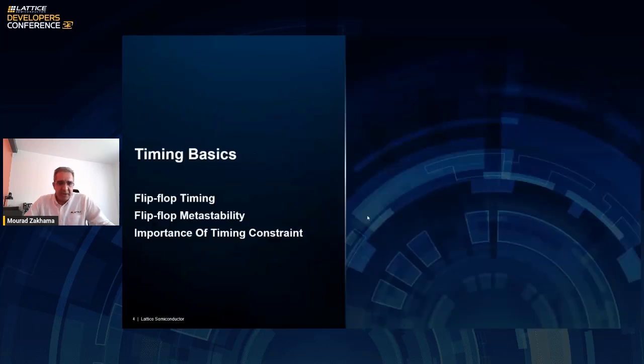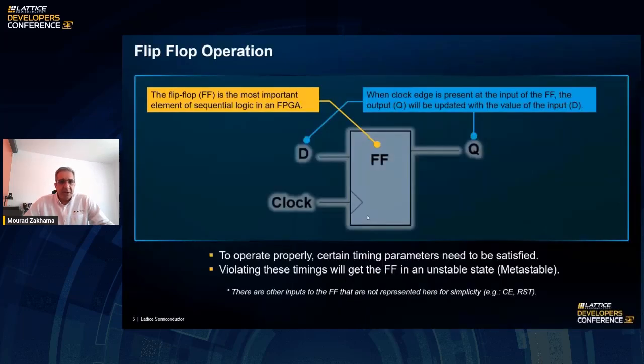So let's start with the timing basics. We're going to talk about the flip-flop timing, the metastability of a flip-flop, and the importance of timing constraints in your design, and their impact on the outcome of the implementation process with synthesis or map and place and route. So I think everybody knows that the flip-flop is the most important element of a sequential logic or a synchronous logic.